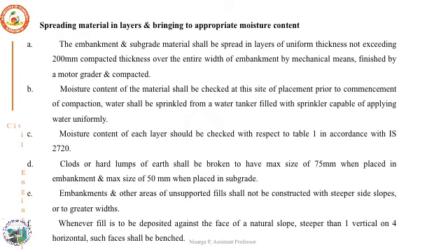You can use the motor grader, and then the compaction will be done. And before the compaction is achieved, we have to check the moisture content. So prior to the commencement of the compaction, you have to check the moisture content using any of the suitable moisture content determination tests. Field moisture quick test can be done.